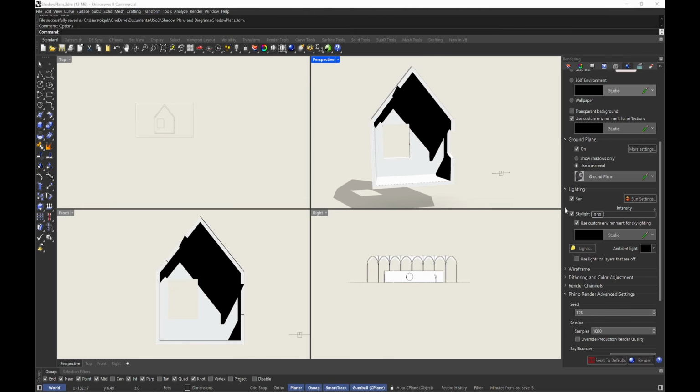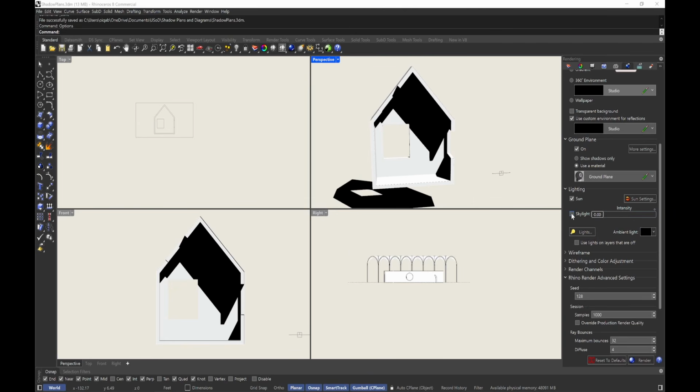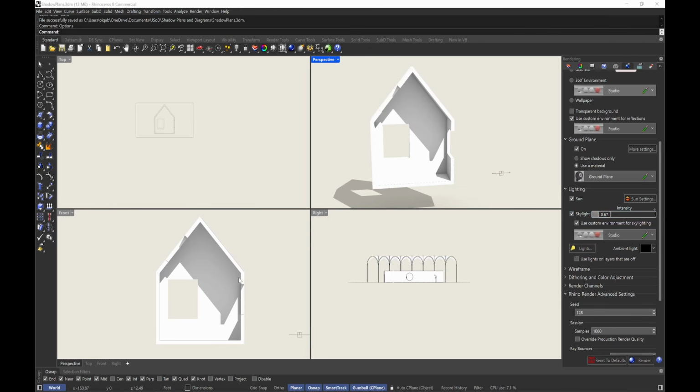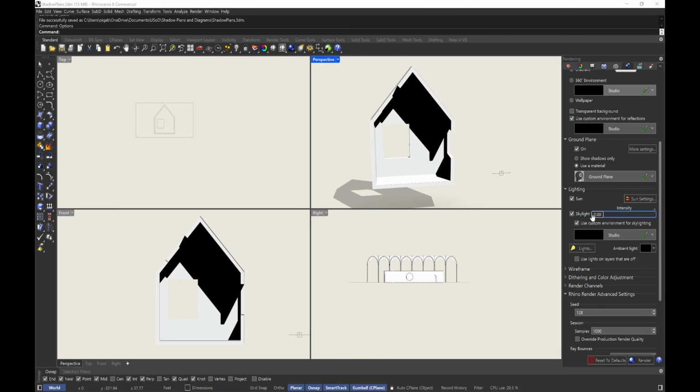And what I'm going to do here is, if you see my skylight, I actually activate my skylight. It's really important that I have my skylight activated. So I activate my skylight and it's your choice how dark you want this to be. If you want it a little bit lighter, you can have it a little bit lighter, right? Honestly, I prefer it to be a little bit lighter, but if you want that very strong contrast, like floor plan black and white and section black and white, then yeah, you want the skylight to be almost zero, if you want that very stark black and white.